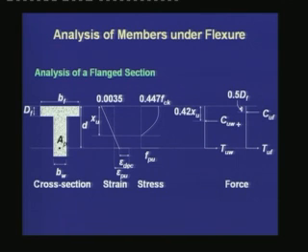Now, once we have drawn the strain profile, we can draw the stress profile based on the constitutive relationship of concrete. For the prestressing tendon, we have to note that the strain of the prestressing tendon at ultimate, which is represented as epsilon Pu, is equal to the strain in concrete at the level of the CGS plus the constant strain difference, which is denoted as epsilon DEC, or which is termed as the strain in the prestressing steel at decompression of concrete.